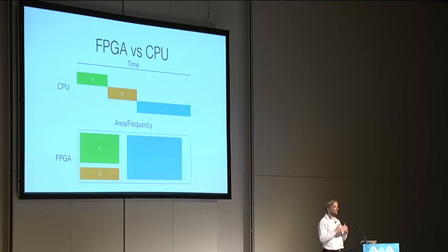The frequency that you can run your circuit at is determined by the worst combinatorial delay that you have in your whole design. So, for example, if you're running your circuit at 10 megahertz, you have a certain amount of time between the rising edges of the clocks, where the registers are storing the data. And if your addition exceeds this time, then your timing is not met, and you cannot use the design that you have chosen to run with this frequency. You have to lower the frequency. This may be possible if your design allows it.